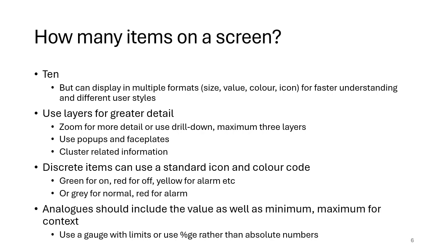So for example, consider a valve. You might have green for open, red for closed. You might say the actual process value that you're controlling, such as flow, if it's a valve, or maybe it's temperature or level or something. So you could have several different values. Maybe you also change color with an icon, maybe a flashing exclamation mark if there's some urgent attention needed, or maybe some other color code.